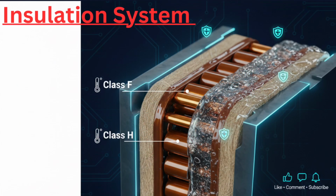Insulation system. The insulation system prevents short circuits between turns, between phases, and between windings and earth, making it one of the most critical factors affecting alternator reliability. Each conductor has turn insulation, slot liners separate windings from the stator core, and the completed winding is impregnated with varnish or epoxy resin to increase mechanical strength and moisture resistance.